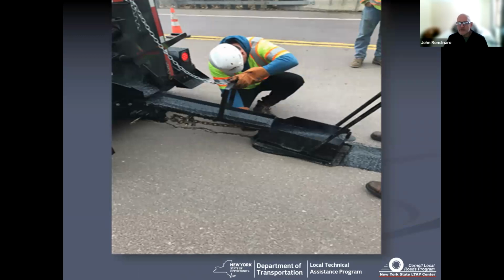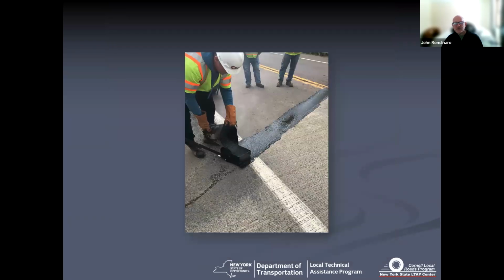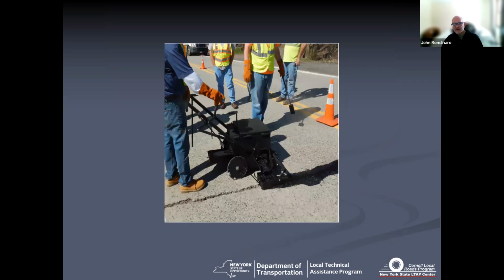And here's the construction operation. You're pouring it out the back of the rig, out of the chute, into a drag box in this case. Because you're doing a transverse crack, you're going to just empty the chute into a pail and do a little more hand type of work, but you're still getting a nice coverage of that crack. And some of the contractors now are using these little buggies that they would also be using for crack sealing operations.